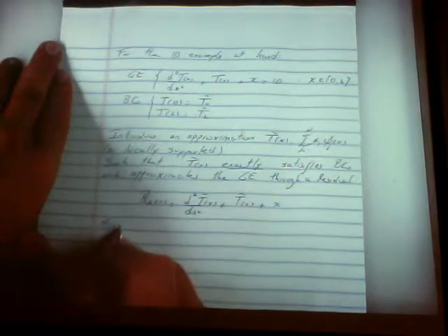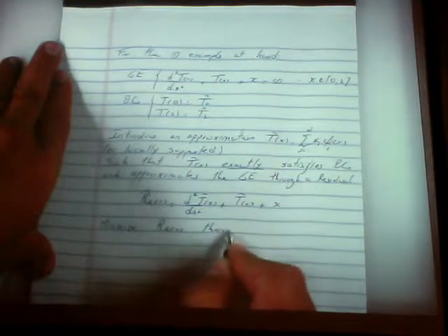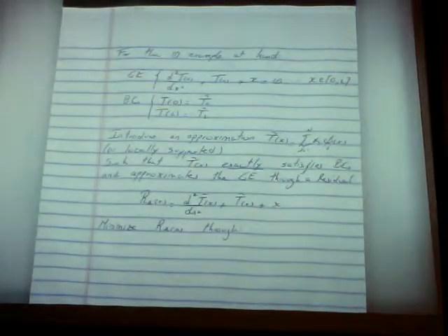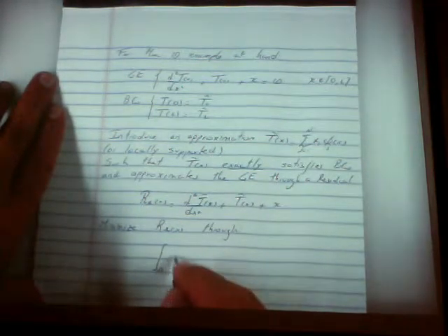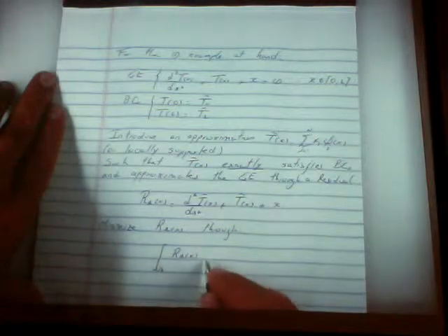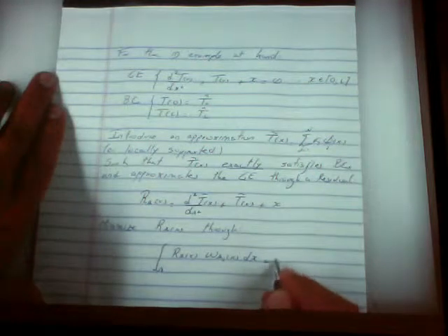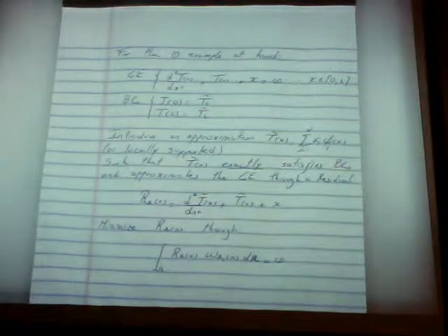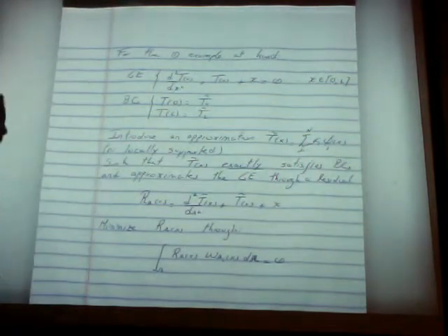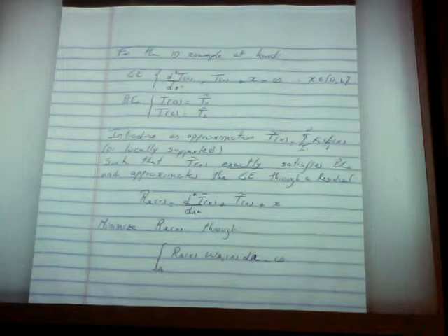Minimize through. So we minimize the residual by requiring that in an integral fashion, this goes to 0. This is the domain. Now we know that the domain is a 1D line that goes from 0 to L, and that because we're going to be using subdomain method of weighted residuals, this turns out to just be 1.